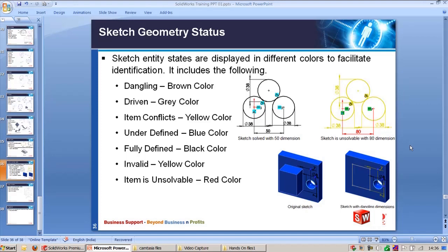If you know only the creation of a sketch, editing of a sketch, applying geometry relations and doing dimensioning without understanding the different colors, that is the geometry status, you will not be able to define the sketch fully to be parametrically controlled. And that's all about the sketcher environment of SolidWorks. I hope this session will definitely give you a better view on sketching 2D entities.